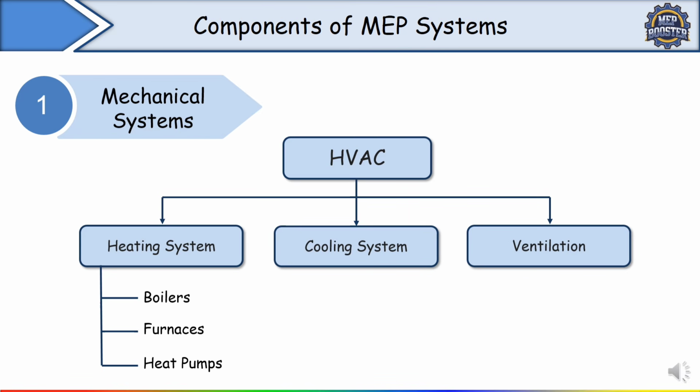So here in central cooling system, the first component is the air conditioning system, okay, like split system, package system, ducted system. So different types of air conditioning systems are there. So a split system generally consists of an indoor unit, evaporator coil and blower, and an outdoor unit also, condenser coil and compressor.